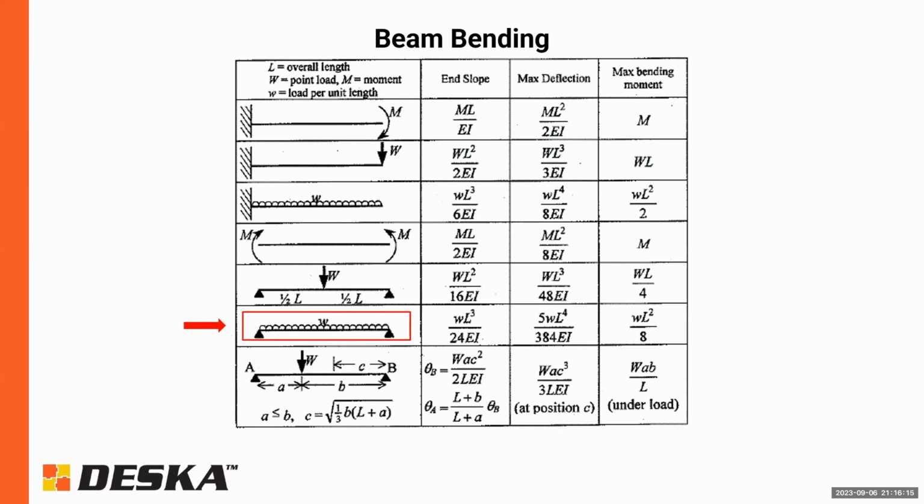And typically the bending stress is what governs when you're designing a beam. You have bending stress, then you also have the shear failure of the beam, which essentially is where the beam fails right above the supports. But pretty much in a residential sense, the failure always occurs due to a bending stress, and that's what causes the beam to sag downward and give that smiling look.